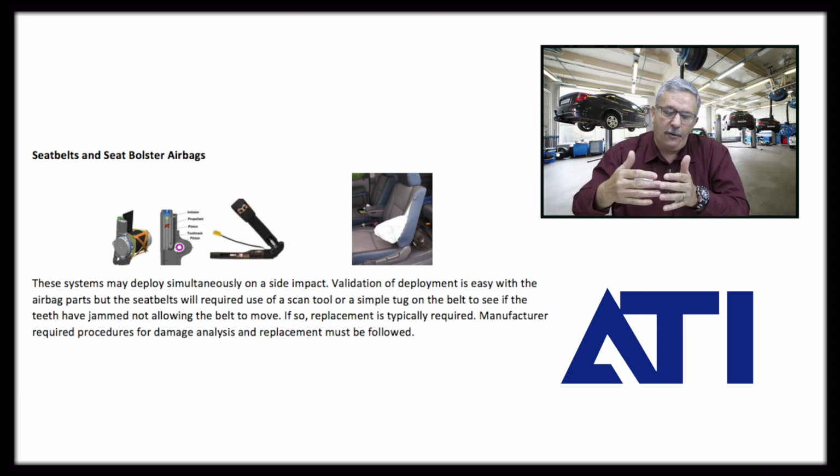If you have that tear, what it does is it allows the bag to move out faster. And even though we're talking about 1/25th of a second, we're talking milliseconds here where this moves, it can change the direction of how that bag deploys. So the inspection process on these parts is extremely important, and I don't think I can emphasize that enough.